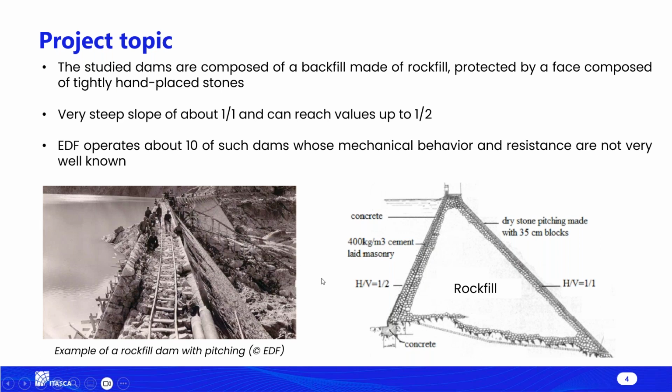In the figures below, I'm showing on the left-hand side the construction phase of a real dam. We can see the dumped rockfill in the middle and the drystone pitching, which is laid on the two faces of the dam. On the right-hand side, we can see a section of this same dam. We can see the rockfill in the middle and the drystone pitching on the two sides, with a transitional layer of rockfill below it.